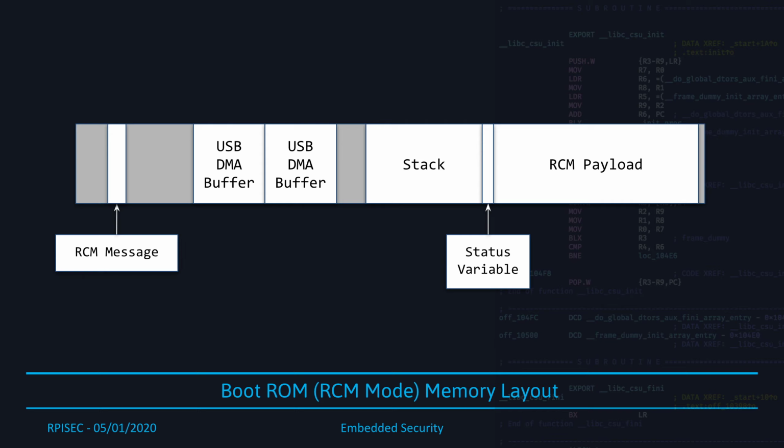You have the USB DMA buffers, where you write whatever packet you want to send. There are 2 of them so that you can be more efficient and not wait, and you can handle multiple different types of USB requests at the same time. So you basically write data into these DMA buffers, and then they will get written out for you over the wire as USB packets.